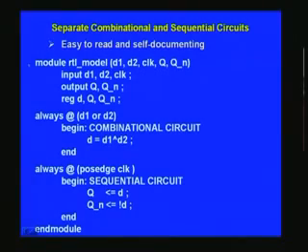Once you have a module, you should signal to the tool that is going to process it by another corresponding keyword called endmodule. Note that there is no gap between end and module. It's a single word. So module, endmodule. This is a vital thing that you have to keep in mind. And once you have identified it as a module, then you have to give a module name. For example, this is a model for RTL, so I'll name it RTL underscore model.